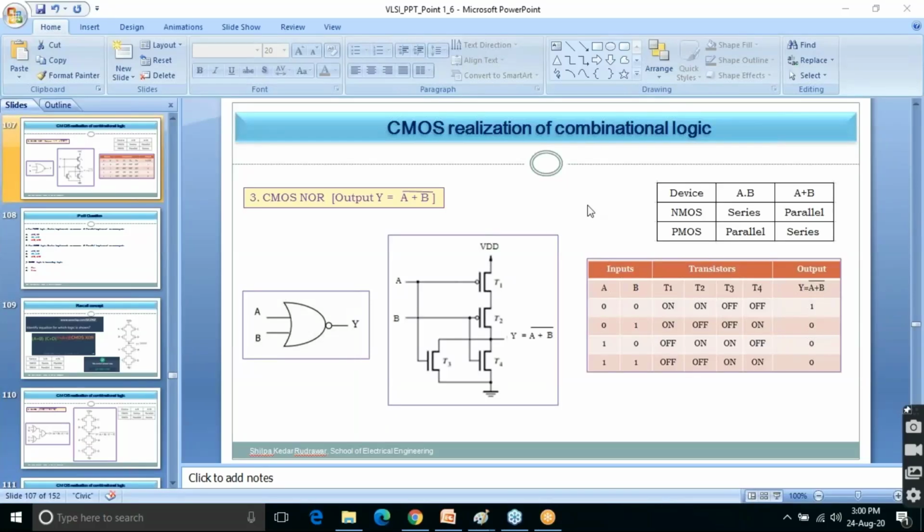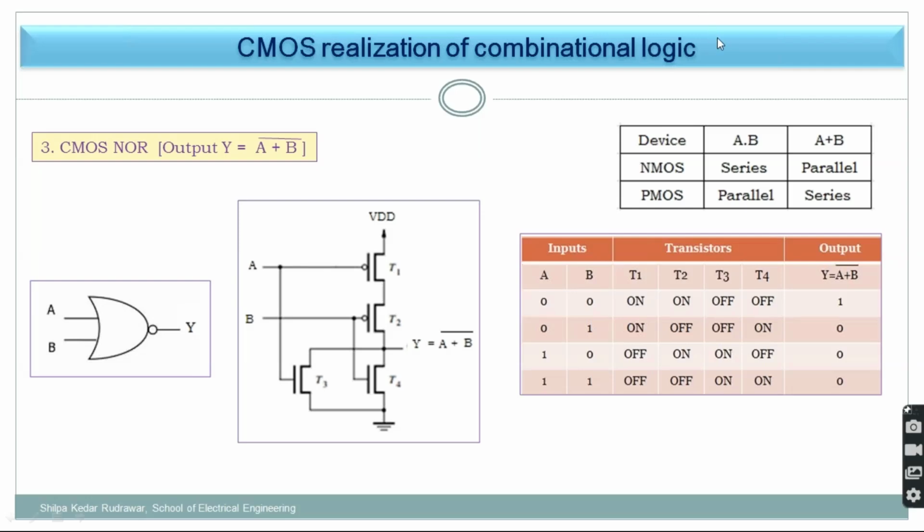So we will start. I will quickly recall some concepts which are very important. In the last lecture we were with combinational logic design using CMOS. As you know, CMOS stands for complementary MOSFET, which has PMOS in the pull-up network and NMOS in the pull-down network, and it implements inverted logic, that is, the complement logic always. Whenever the bar is given over any expression, you can implement that particular function directly, as I told you, and we have taken some poll questions on that also.